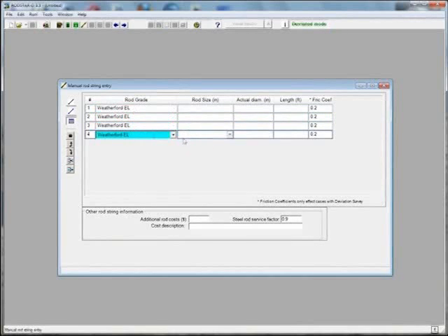See, that's a fast way of putting the same rods in there. For the rod diameter, the same thing. The program actually defaults to 1 inch as the top rod. If that's what you have, which is what we have here, that's fine. If you click in the next field, it will automatically put it to 7/8. If you click on the field below, it will automatically put it at 3/4.